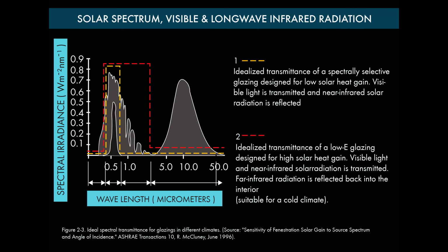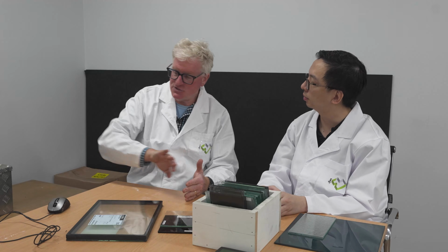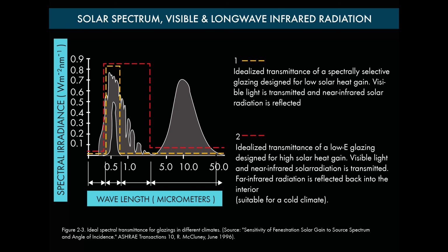A low E coating is rejecting the solar spectrum, the heat portion. The infrared, the long infrared, the long wave, and possibly the infrared and the long wave spectrum. We have to look at those properties of the glazing system. But it's after the heat has passed through and it's heated up a surface, and that surface wants to emit or radiate to that glass, which has a low E coating. And the glass is saying, no, I'm not going to accept your heat. That's typically in the far infrared spectrum.